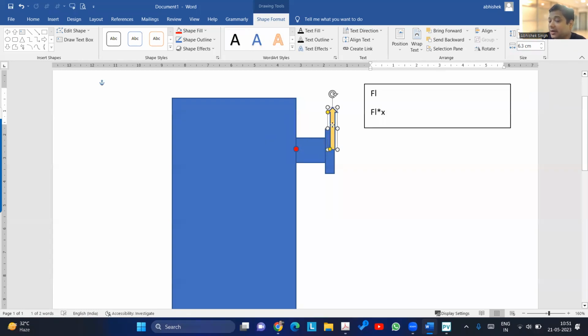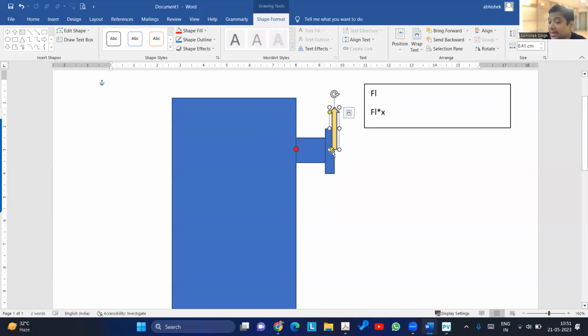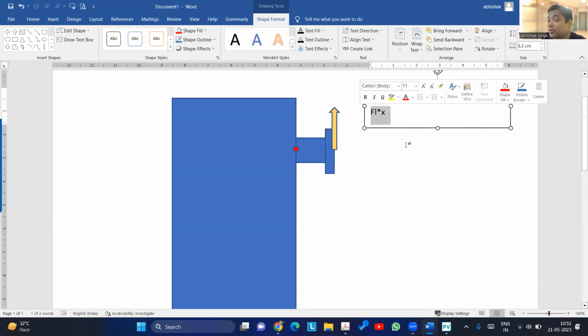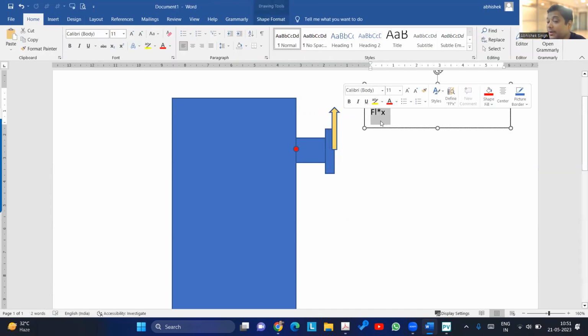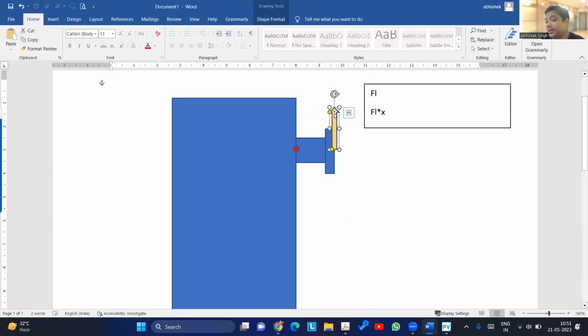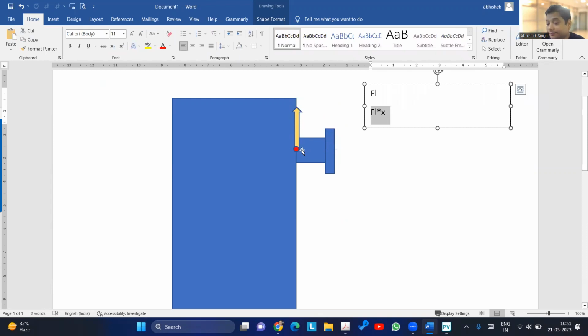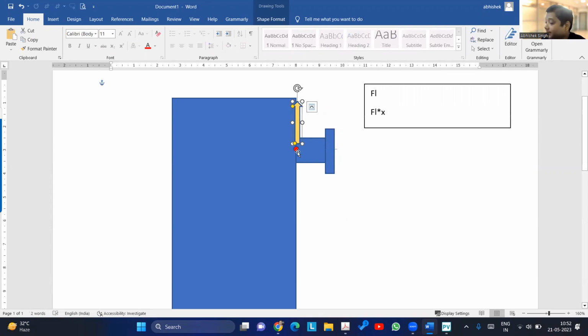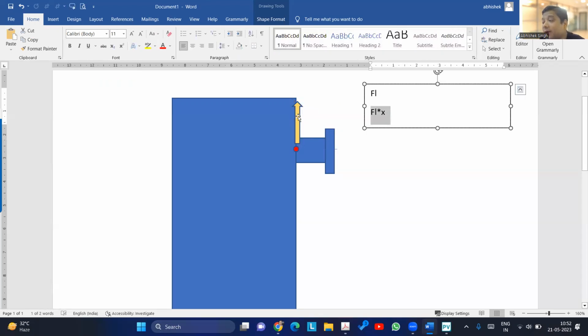Here it was only the FL load. There was no moment at this point, but at this point, this was the moment created by this. There was no additional moment, but this moment was created by this force at this junction. Now, if I just shift it here, then this moment is gone. There is no moment created by this FL about this point. So this is gone.